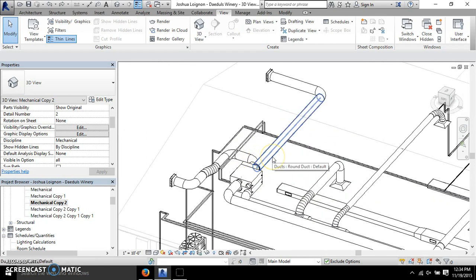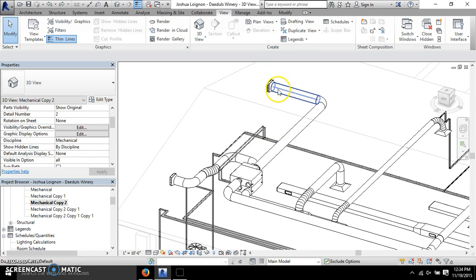If it's more of a development and they're just trying to get the building up quickly, and they're more worried about earning money than architectural design, they'll just put the louvers wherever so that they can be seen. But typically, you want to try to hide them as best as you can. And there's a certain distance that exhaust air has to be away from air that's sucked into the building. So this is fresh air coming in, and this is exhaust air being put out. Obviously, you don't want these right next to each other because exhaust air would be thrown out and then sucked right back into the building.